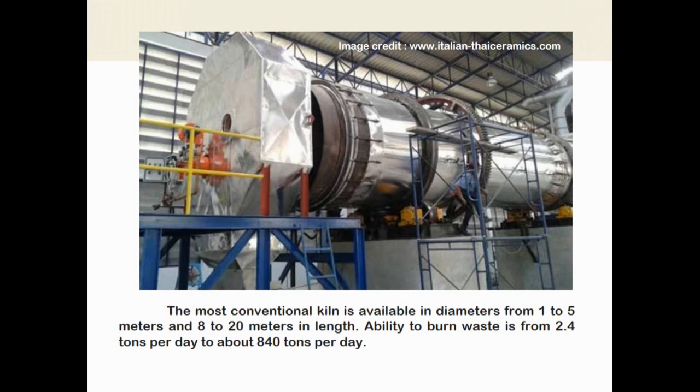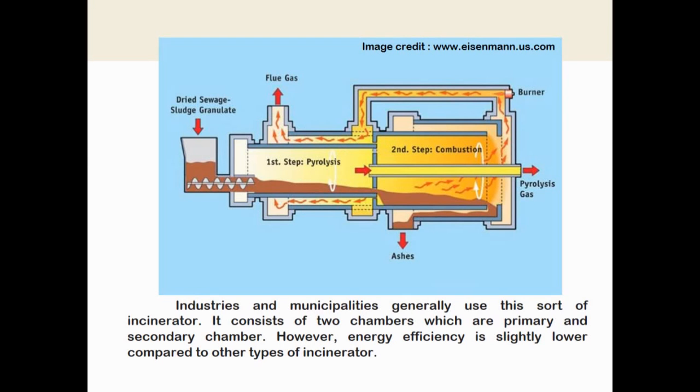The most conventional kilns are available in diameters from 1 to 5 meters and 8 to 20 meters in length. Ability to burn waste is from 2.4 tons per day to about 840 tons per day. Industry and municipalities generally use this sort of incinerator. It consists of two chambers, which are the primary and secondary chambers. However, energy efficiency is slightly lower compared to other types of incinerator.